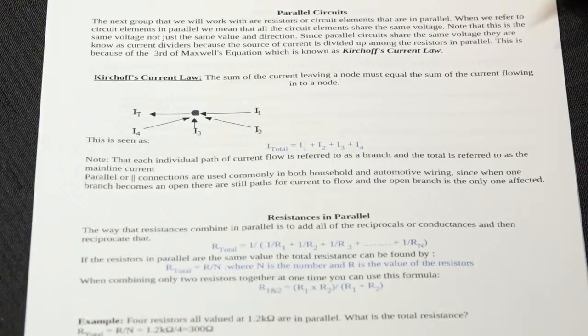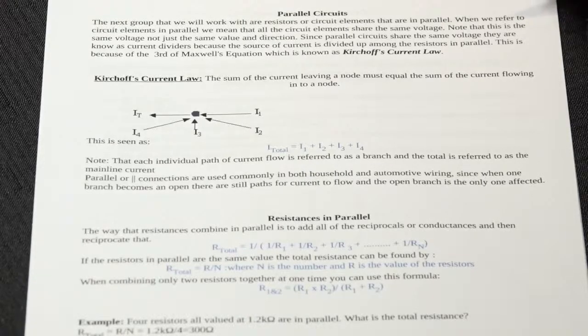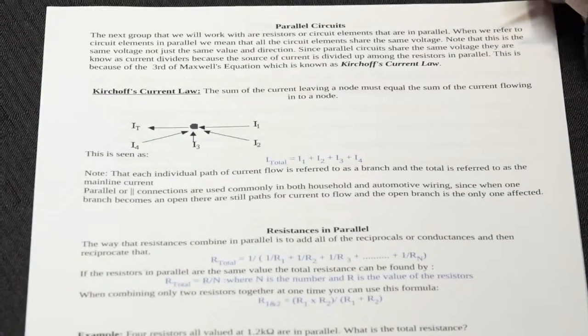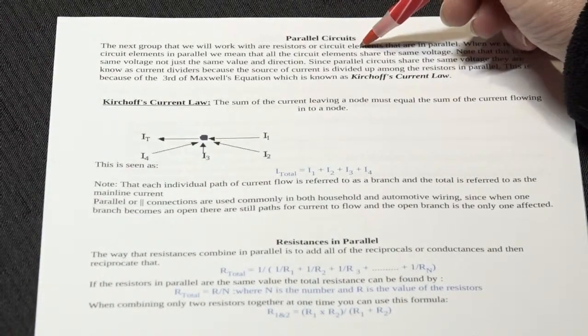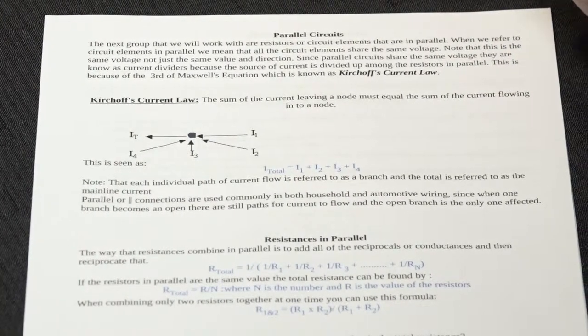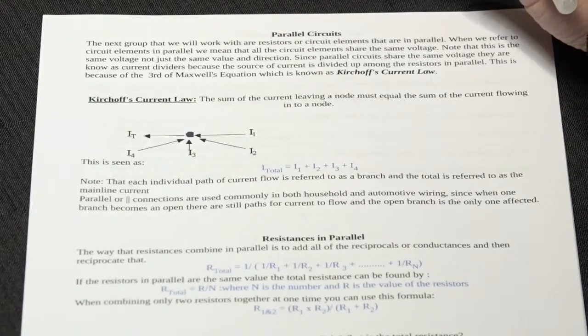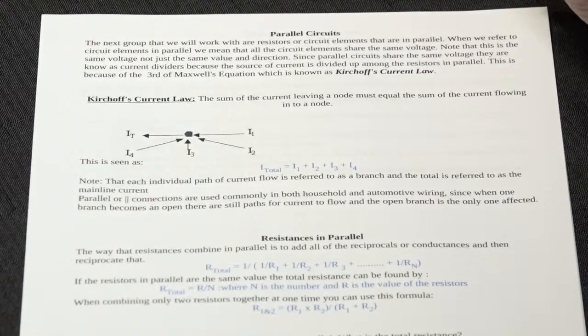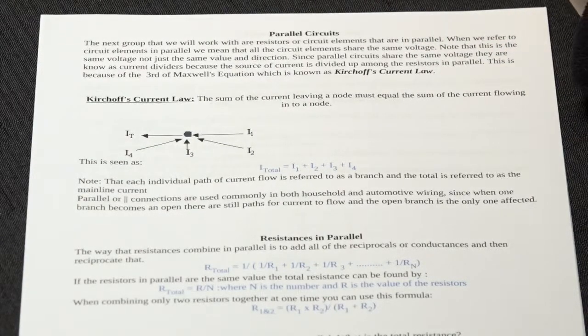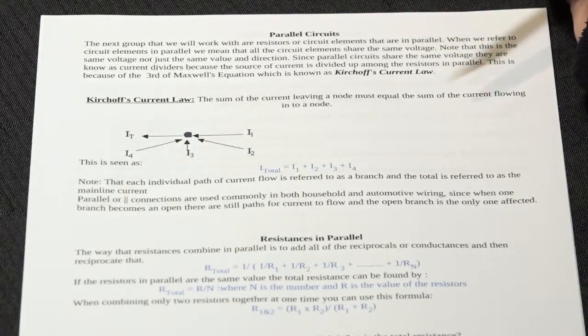And welcome to part 2 of our week 7 lecture series, where we have already talked about series circuits. Now we're going to talk about parallel circuits. How do you know something's in parallel? Unlike series circuits that share the same current, parallel circuits share the same voltage. And because they share the voltage, they divide the current.